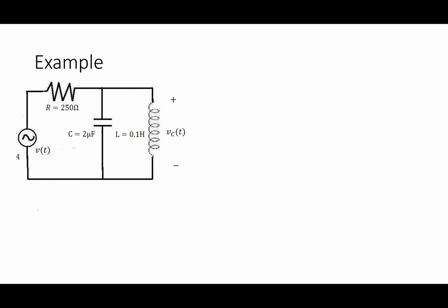So we talked a little bit the other day, and I said, all right, if I look at a capacitor and inductor, so V sub c and I sub c, the relationship that exists for those in the time domain is what? I sub c equals C dV c dt. That's our time domain relationship.